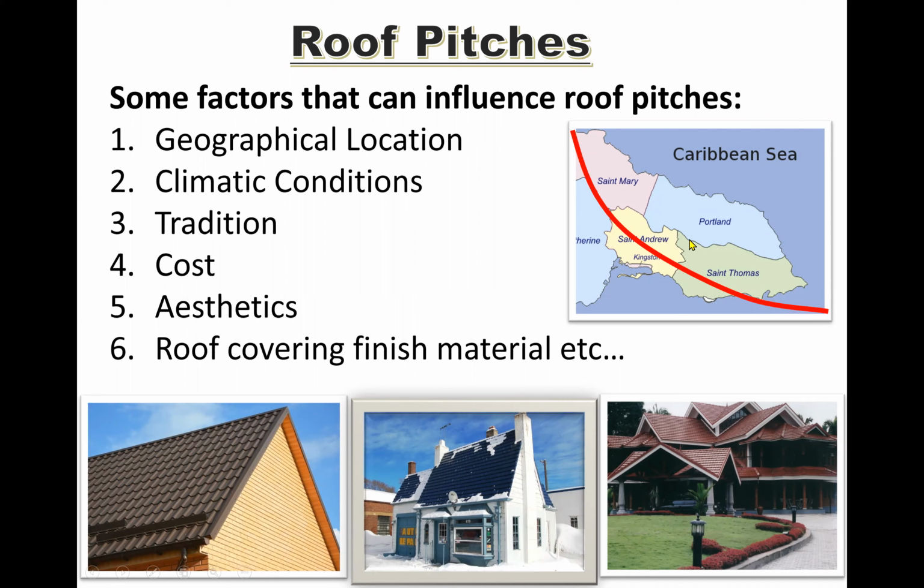So what that is telling us is since those areas are impacted first, persons who live on that side of the island should really consider creating roofs that are a little steeper so that the wind does not get underneath the eave of the roof and lift it off easily. So instead of creating your roof too shallow like that, you would want to create it a little steeper so the wind doesn't get underneath it easily and lift the roof off. So geographical location would be a factor.